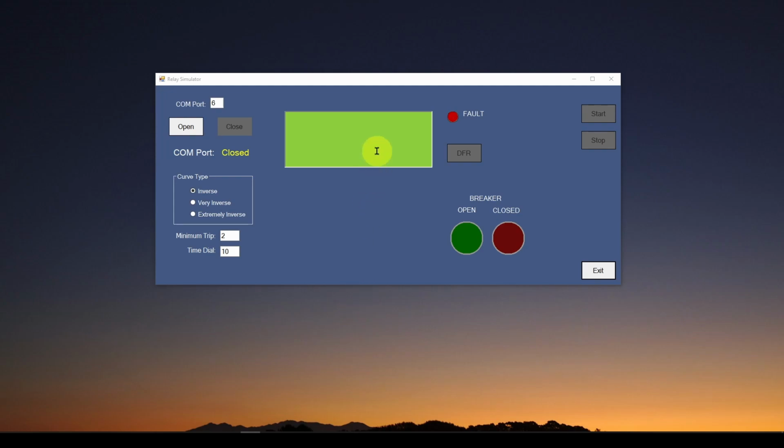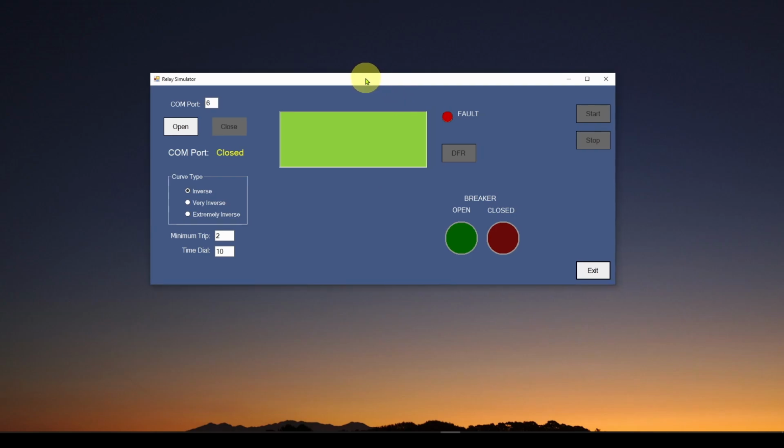Their job is to monitor the electric circuits continuously. And when they sense a problem, they will generally start a timer. And if the problem still exists after the timer times out, they will perform some action. Generally that action is to open a circuit breaker to de-energize the power feeding your home and your neighborhood so that it can be fixed and then the power is restored.